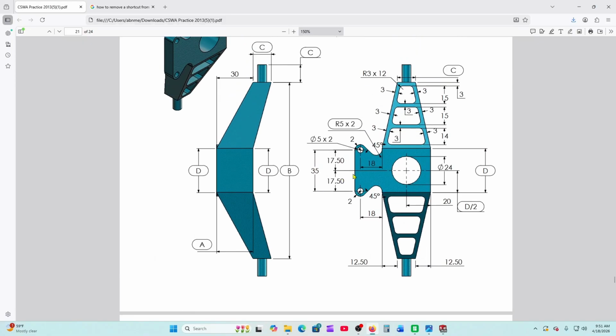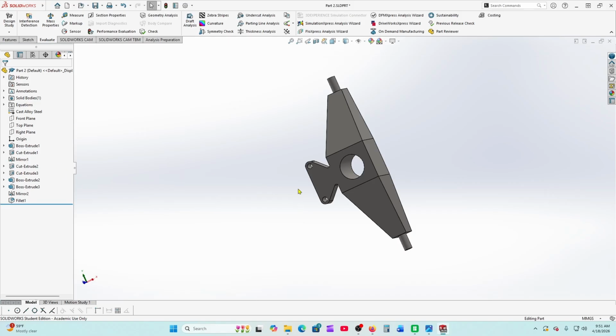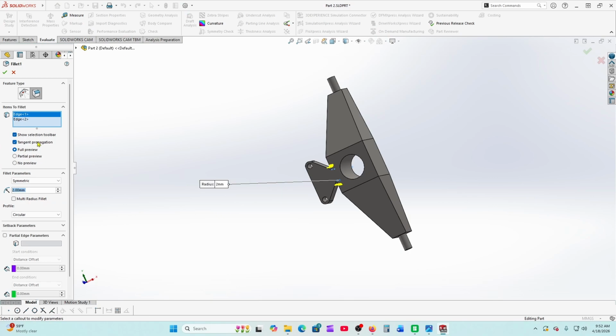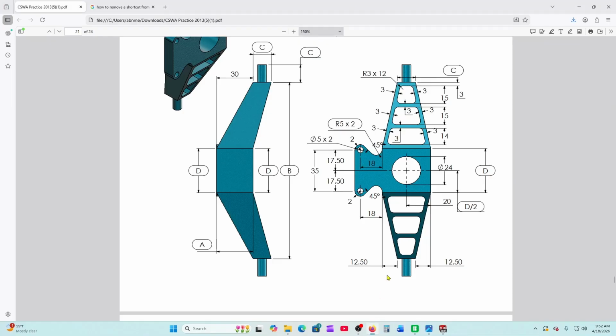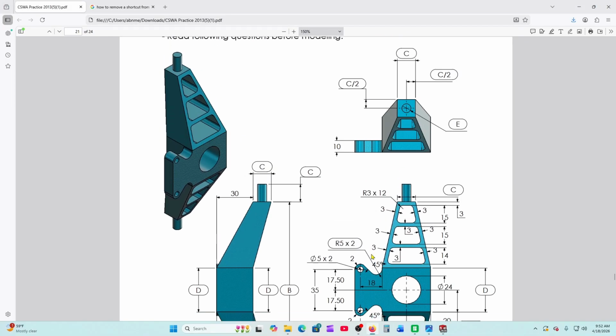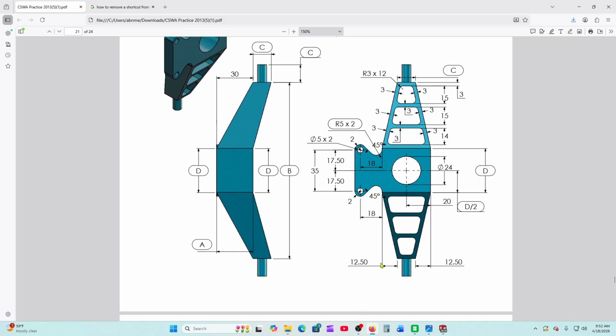All right, so we got to change the radius here to 5. So let's go ahead and do that while we're in here. So I'm going to change the fillet here to 5, like so. And then what else do we have? Everything else would have updated. So the only thing that we need to do right now is add the radiuses in there for all that.